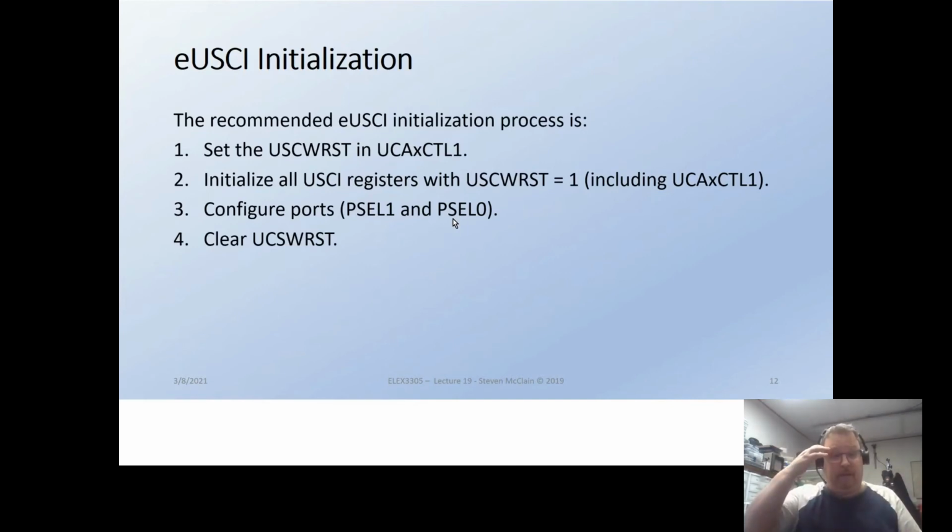Now, if your application or device works in such a way that you need to power it down and leave it powered off for a bunch of time, and then you power it up and do things, then you might need to reinitialize it. There are some CPU low power modes where you lose initialization, and so you have to reinitialize them when you come out of that low power mode, but we digress. In general, set it up once and then start using it. You never really have to set it up again.